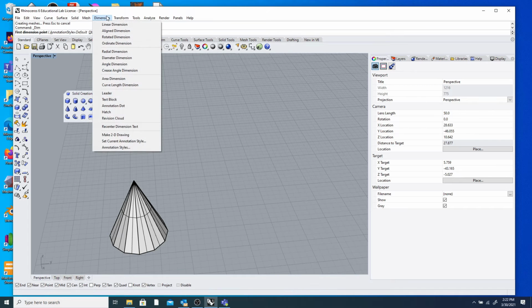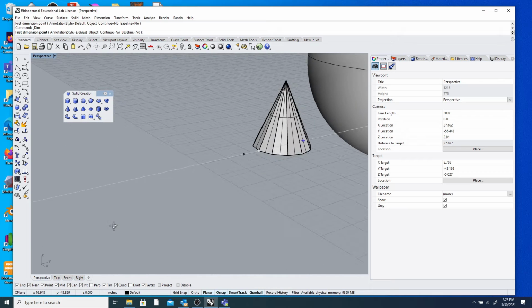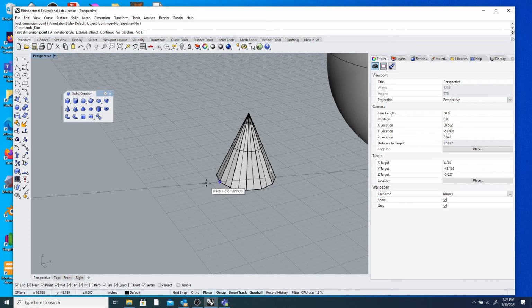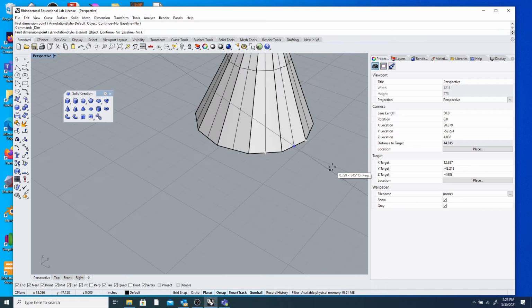So that menu just across the top, this is how I've usually accessed it in the past. I'll just click up here. I just want to see the width of this thing, so linear dimension, and you can see how it's snapping to 2 points. It's showing me that's an endpoint, midpoint, endpoint, right? Those are called O-snaps or object snaps.